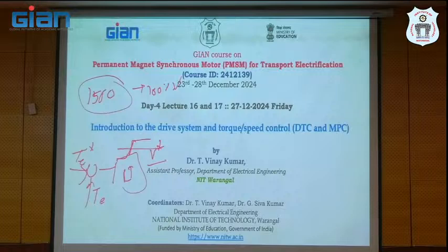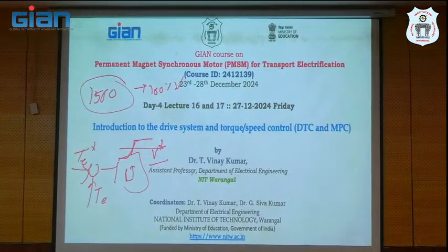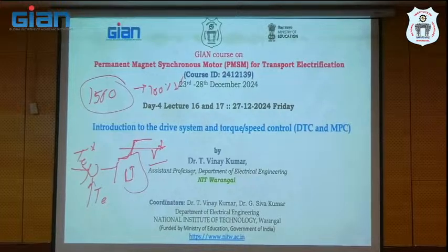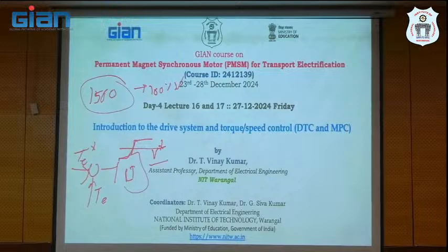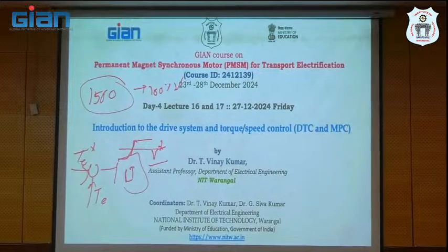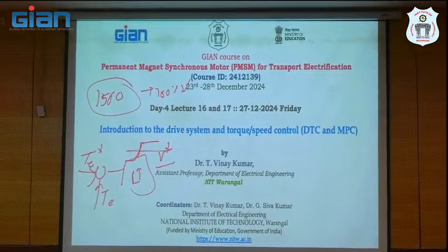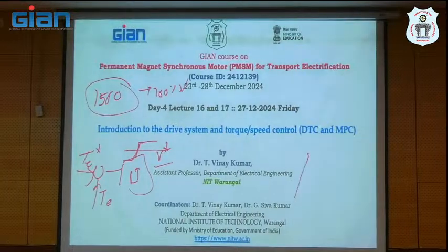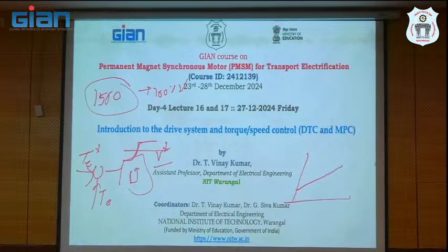If the speed of the magnetizing poles and the speed of the rotor are very far apart, the relative motion is more and you will not get twisting force. Back EMF is 0. There is no twisting force, there is no mechanical energy, back EMF is 0. The machine will take a huge amount of current. That's why, if it is open loop, you have to write the program to get step voltages. But in closed loop, your logic itself will produce this type of voltage, irrespective of the reference speed. Please understand.